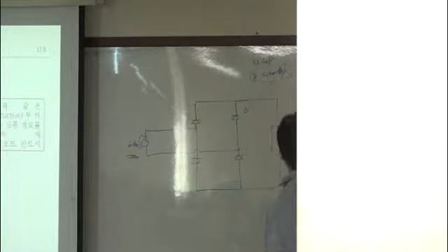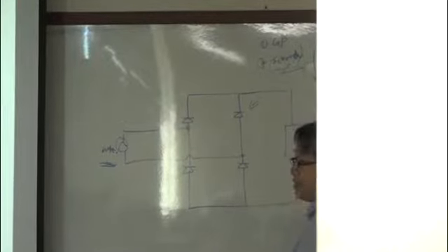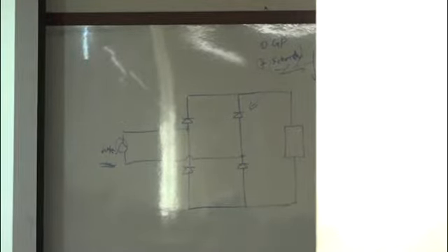Can you apply Schottky here? Or fast recovery diode here? You can use it. But the problem is that we know that diode has forward voltage drop, right? Usually, when your operating frequency is fast, your VF is also increased.